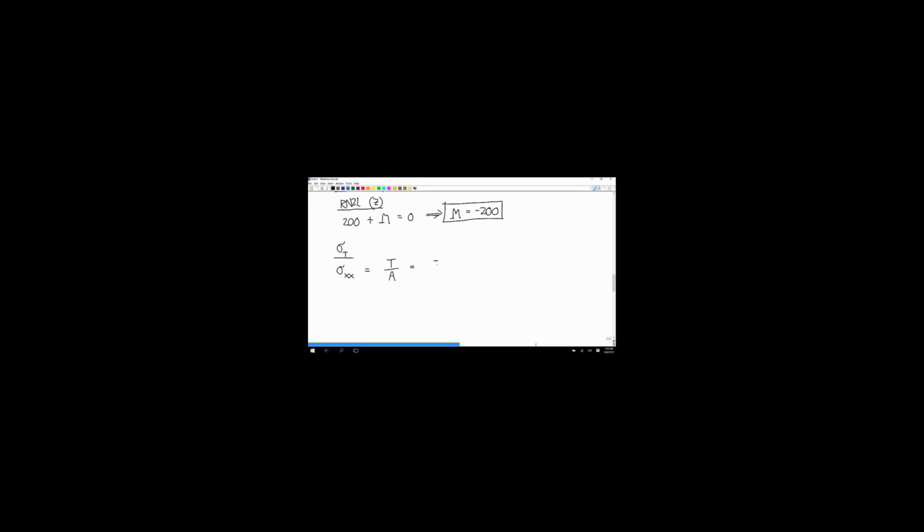The internal tension is the same at every point inside the beam, except for the ends where we're not able to calculate anything, but St. Venant's principle says that's all right at the other places.